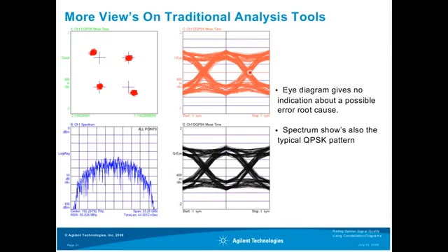These two signals can now be used to compare with the original measured signal, and this exactly leads to our error vector. If we have both of these signals, we can make additional error analysis tools based on these two kinds of signals and look in various ways at our transmitter signal. So what can the error vector magnitude tell us about the transmitter?